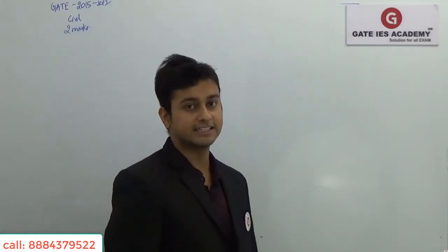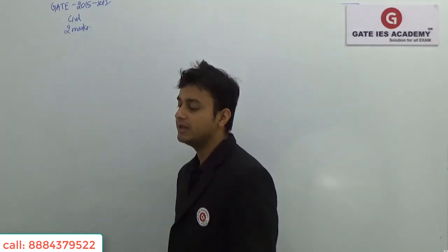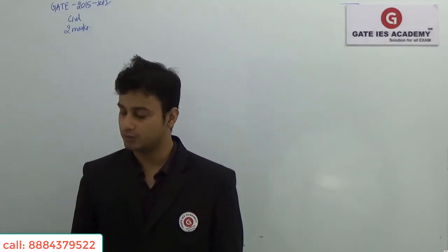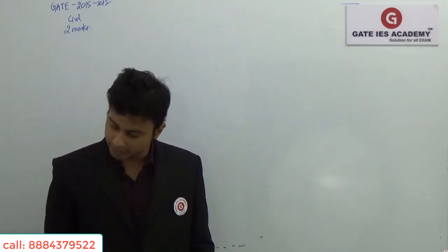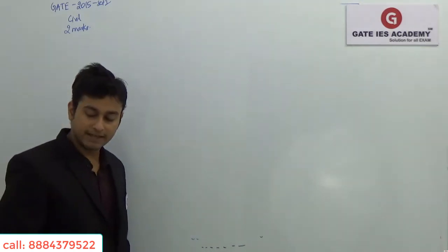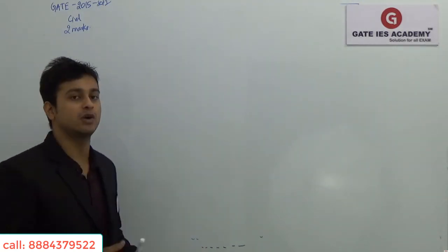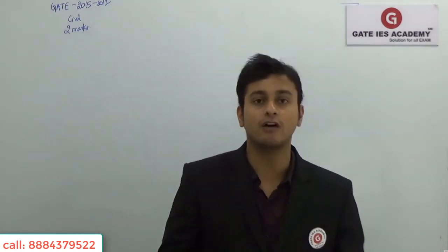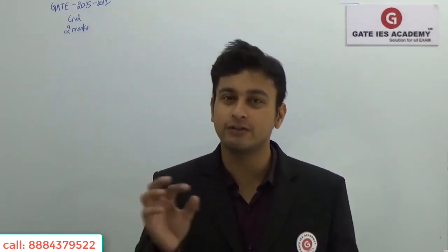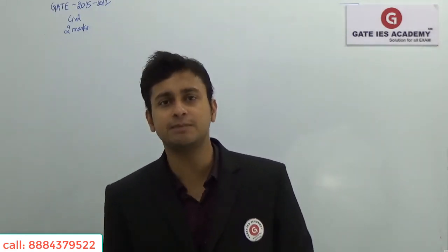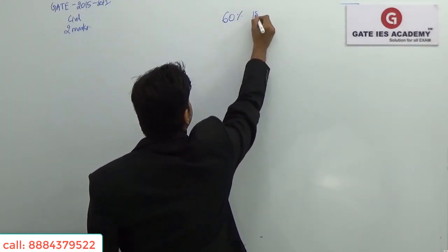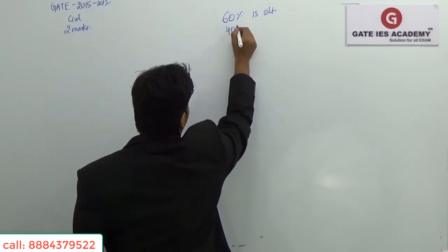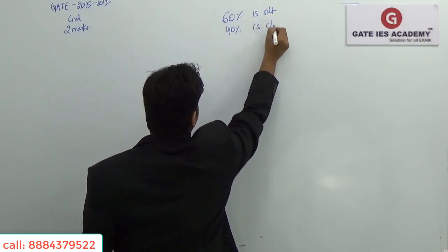I want to calculate the activity. The options given are 3.33, 0.30, 0.42 and 0.2. Okay, so basically this is a fine-grained soil. So fine-grained soil will have a majority of fine-grained particles. Obviously, yes, there will be some coarse-grained soils also mixed, but it is saying that the majority is fine-grained soils. 60% is silt. So 40% will be clay. Isn't it?